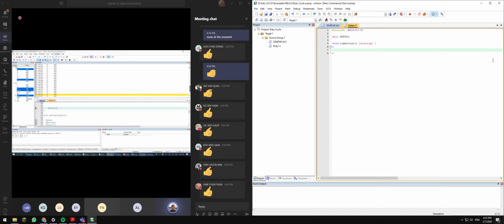Remember the layout of MPLAB X and Keil uVision is definitely a bit different. This one is so interesting. I have Peripherals, I can open the input output. Let's say I'm using port 1, I can use port 1 and toggle it myself. Let's say timer, I can see all the timers, just click on it. It's so easy. Whatever is displayed here is tied to the microcontroller that you are using. It's very, very user friendly.